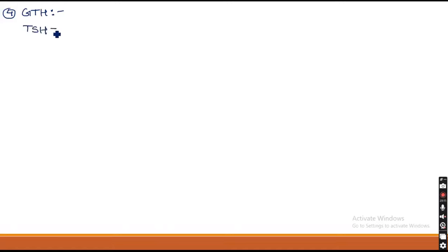Now there are two types of sensible heats. One is room sensible heat, another one outside air sensible heat. So room sensible heat plus outside air sensible heat. Now room sensible heat is given to us in the problem. It is 50.